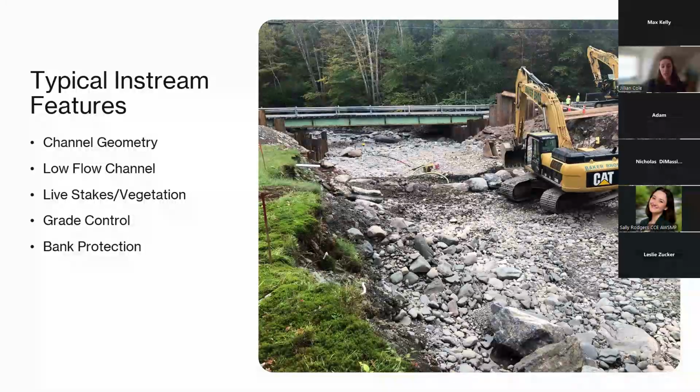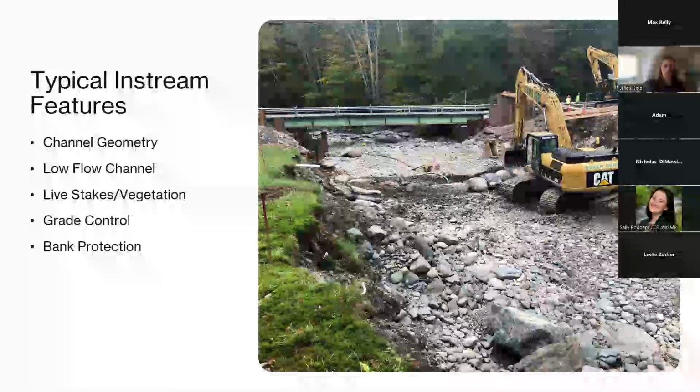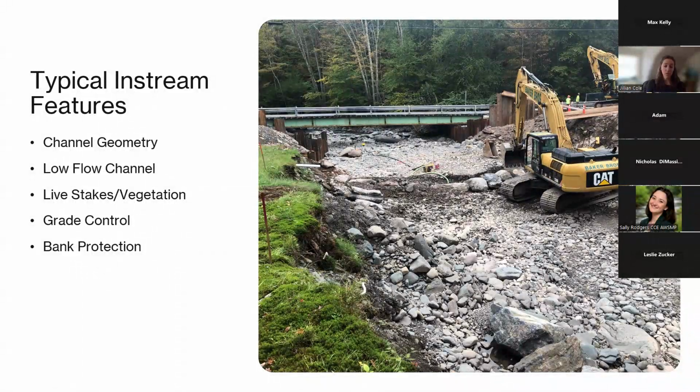Additionally, if bed degradation is a concern, so if there's a potential for head cutting, grade control upstream and/or downstream of the crossing can be installed in conjunction with the crossing. That's what you see here in this picture. There's a series of boulders placed across the width of the channel, and it's placed at grade and then buried, and that's to prevent head cutting as well as to promote indirect flows through the middle of the channel and away from the abutments and the edges of the channel.